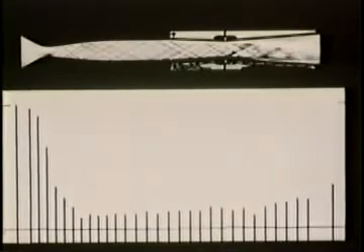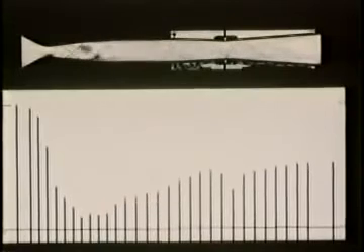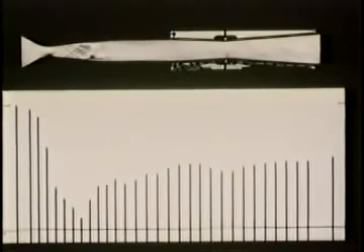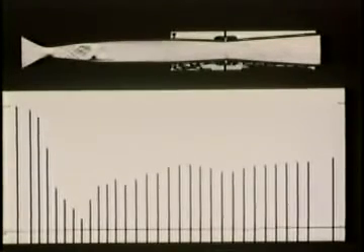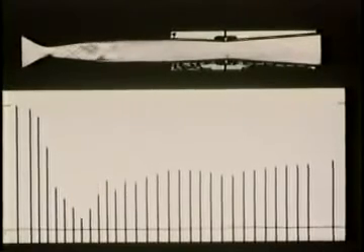By increasing the back pressure sufficiently, we can unstart the channel, or disgorge the shock wave. And we can restart by again opening the valve.